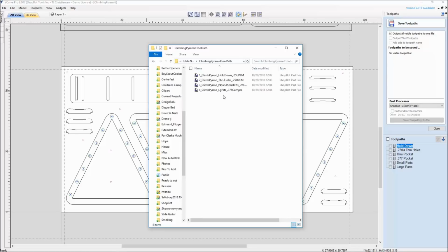But yeah, just come up with a system that works for you. Stay away from the special characters. Order them. Keep the name in there, what the type of cut is, and then also what bit it is. So now when I walk out to the ShopBot, and maybe I'm not going to get to this till I design it today, and I don't get to actually go out to my shop and cut it for 3 or 4 more days, I really don't want to spend another 20 minutes back and forth with the CAD file. I want to go, oh, okay, yep, this is it.